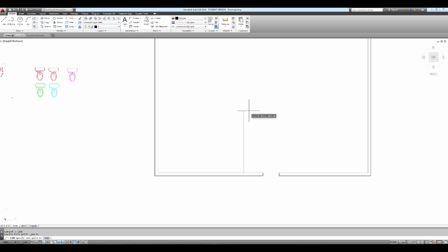We'll come up and draw this up and kind of come over like this, and use offset again, 4.5 inches because it's an interior wall. Use fillet with a radius of 0. Fillet those. Trim this stuff up. Okay, so something like that.